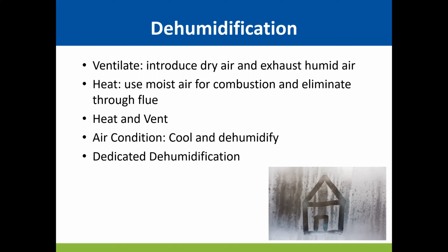But if we do use the air from inside for combustion and eliminate those byproducts, including water vapor, to outside the greenhouse, or even the warehouse, I guess, for that matter, then we can actually reduce the water vapor content of the air.